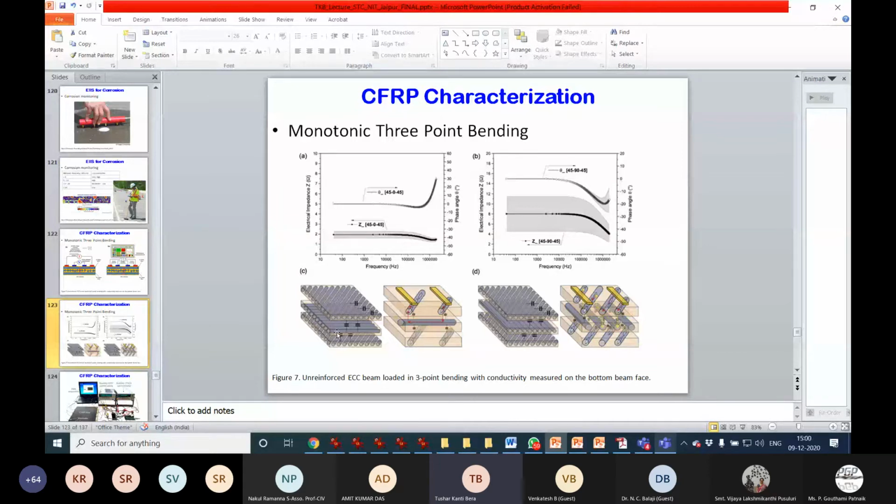Depending on the fiber direction, the current path will be different, and the capacitance arrangement and resistance distribution will be different. There may be several layers, symmetric from a center, from say 4 or 5 to even 10 layers. If we have the proper impedance profile, and if the material is under any damage, any delamination or crack, that type of study was conducted during my postdoctoral studies in Saudi Arabia. We found that impact damages are possible to detect by impedance spectroscopy, and delaminations are also possible to detect, because delamination means there will be a lot of air void in between.